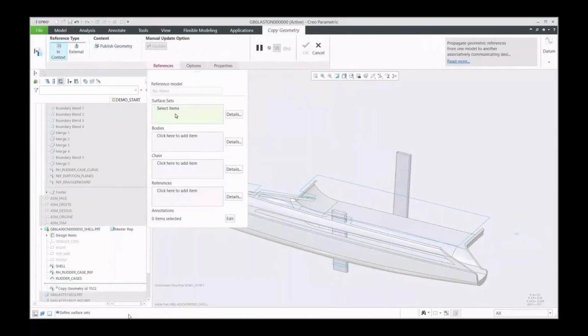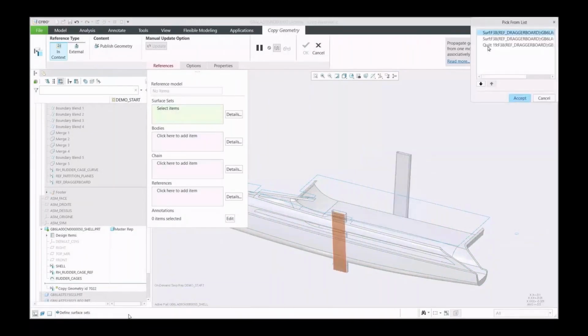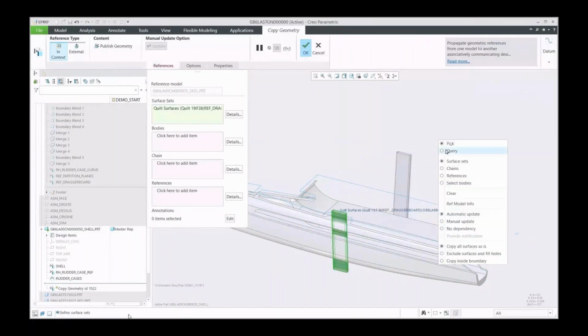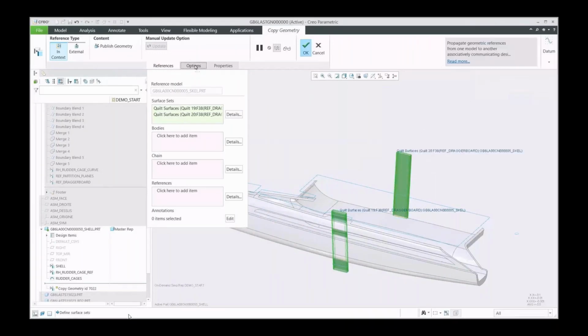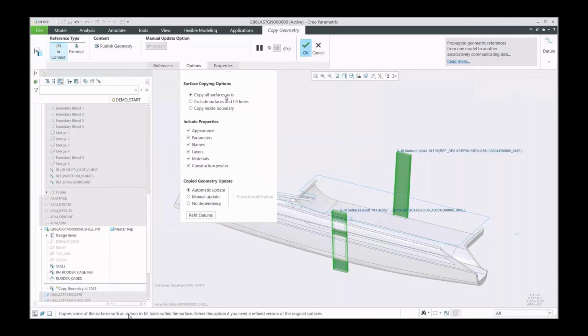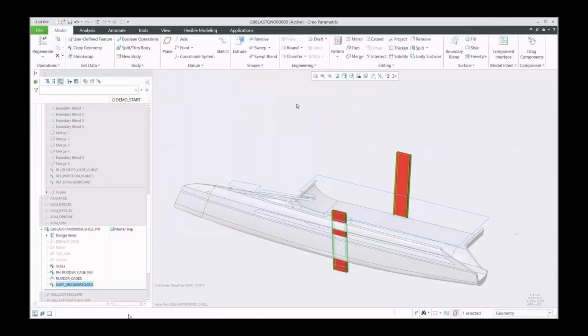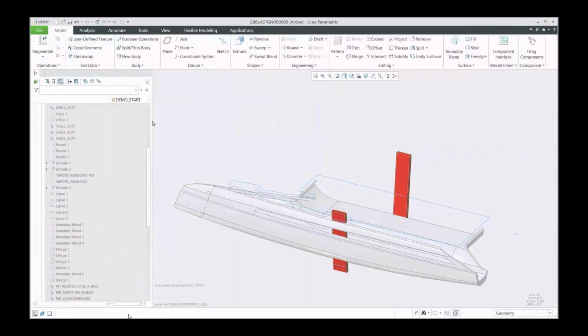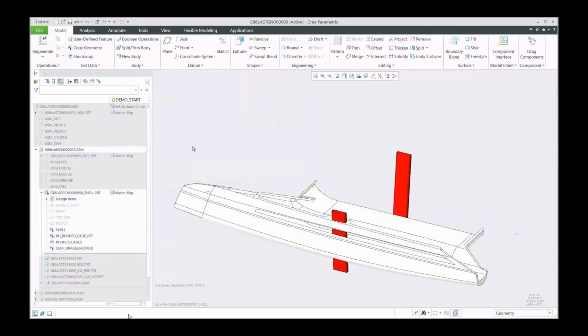And another method of copying geometry, rather than selecting published information, you can actually go in and choose individual information. So I can actually manually go and pick from my skeleton. And that's something that you get to determine in your own workflows. You can make logical sense of when you should be publishing and sharing data en masse or making local references like this. So what I'm doing, pulling some information across from my sub-assembly, and now I'm working on my part.